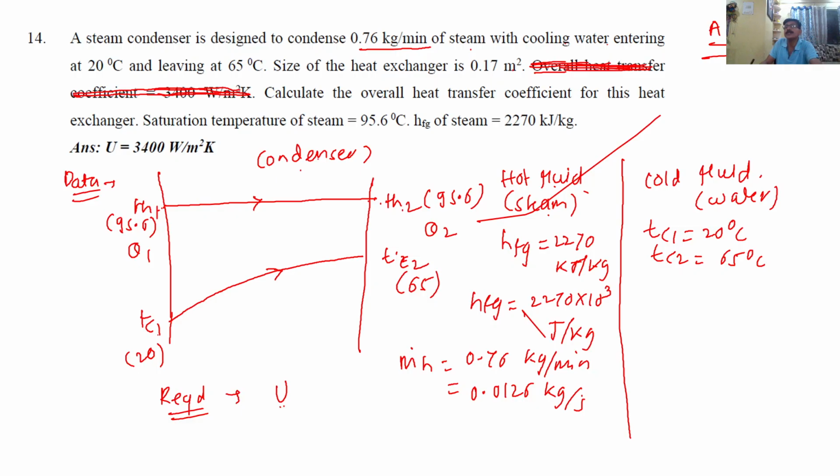Now this one exit temperature I got, for the hot fluid. Now I need to know the second exit temperature, for the cold fluid. That can be calculated by the heat balance equation. M dot h Cph times TH1 minus TH2 is equal to, for the cold fluid, M dot c Cpc times TC2 minus TC1.